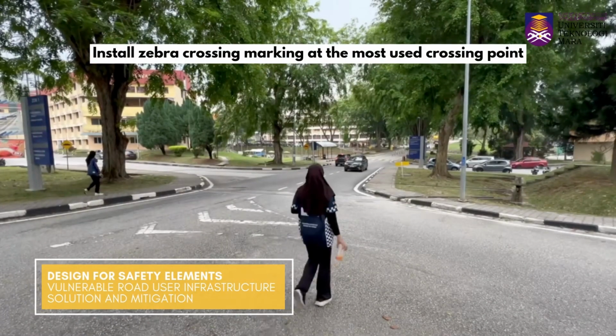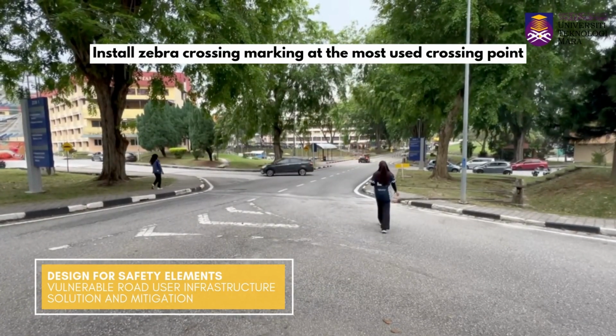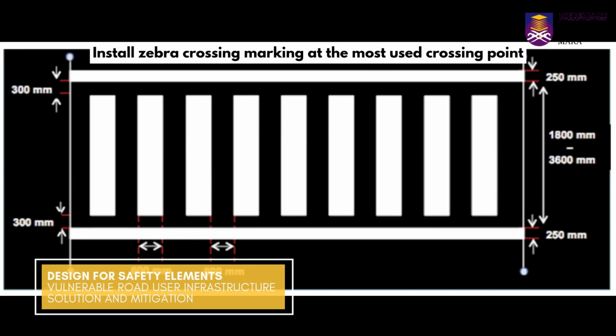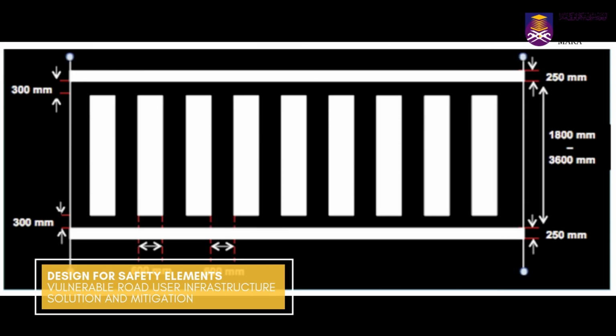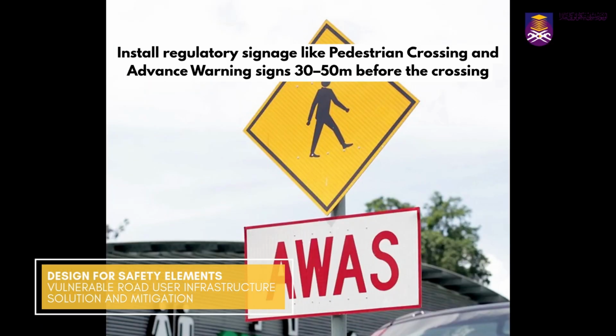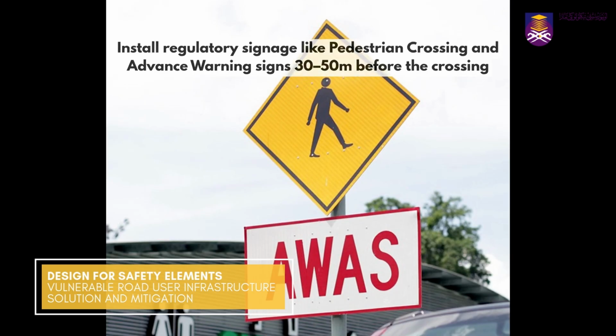Based on the problem, the proposed solution is to install standard zebra crossing markings, which are white stripes with high reflectivity thermoplastic paint at the most used crossing points. Then install regulatory signage, which is pedestrian crossing and advanced warning signs at least 30 to 50 meters before the crossing, as per JKR guidelines.